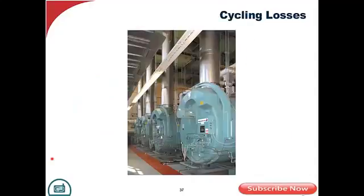What about cycling losses? I'll tell you, this is one of the worst culprits as far as energy loss is concerned, cycling. Where boilers have been put in maybe years ago, they still have a lot of useful life, but they don't have proper turn down, they haven't matched that load. We've done a lot of things to the process, we've done a lot of things to the building, it's much more efficient, and these babies are cycling, turning on and off 15, 20 times, or more than that, an hour. And as a result, we are blowing energy out the stack, we're blowing dollar bills out that stack because of all the cycling losses, cycling on and cycling off.